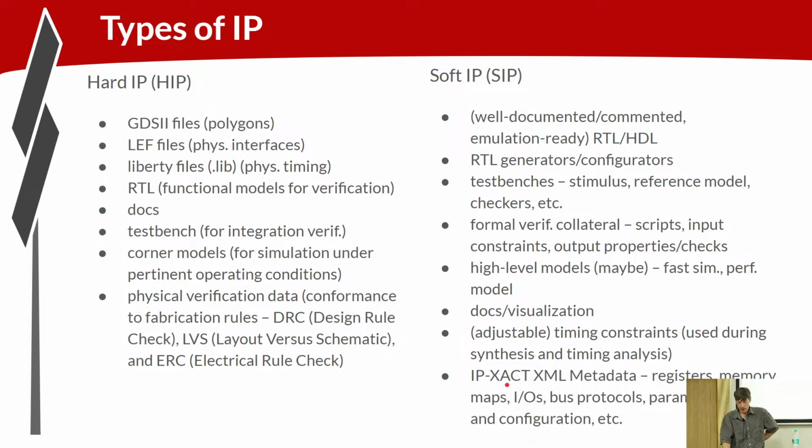IP-XACT is a methodology for integrating IP. The IP-XACT standard defines formats for specifying interface properties of your IP to help with the integration of that IP with other IP blocks. So things like what control and status registers are supported by my IP.